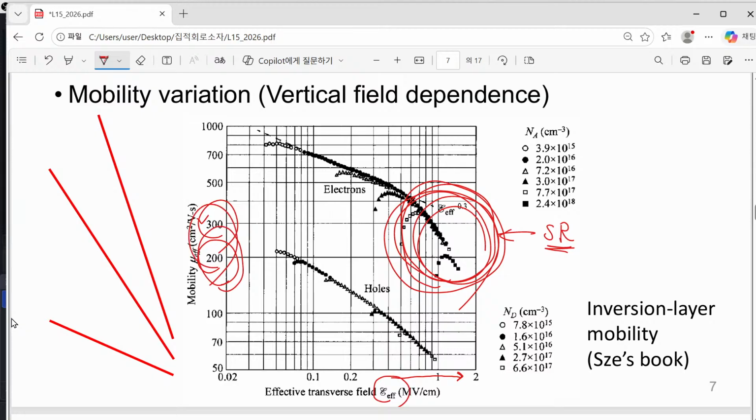But when you study your bulk electron mobility in silicon, the number you have seen was about 1430. That was the value in our quite high quality silicon. So compared with this bulk value, you can find a significant reduction of your effective mobility.